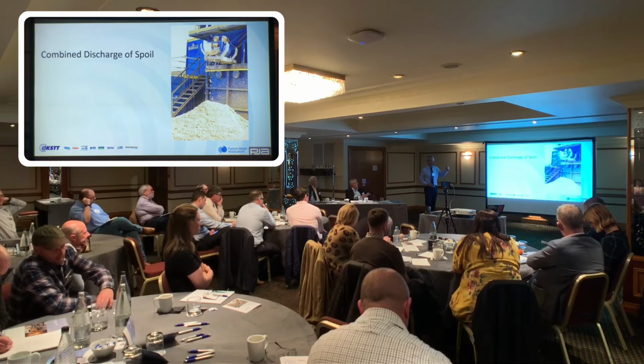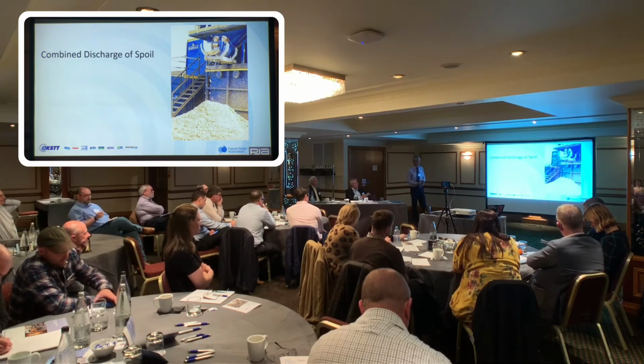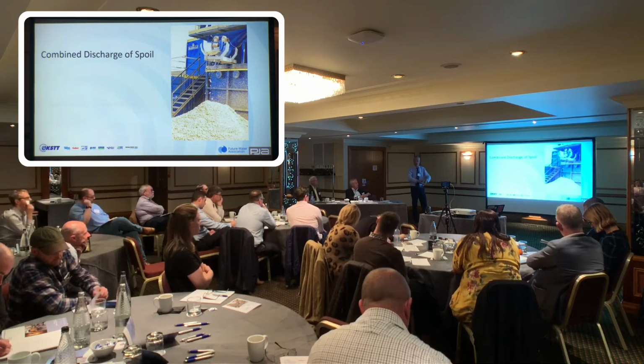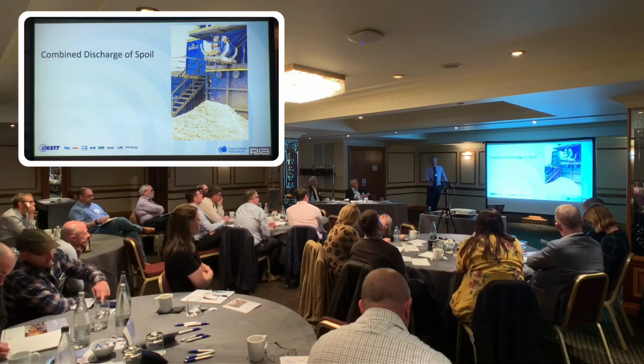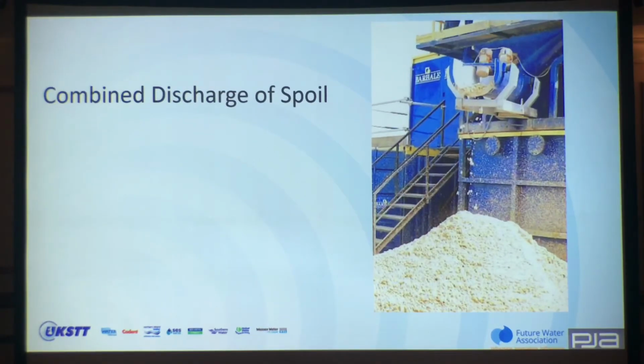And then after all of these processes, the spoil is recombined. So what you don't really want is all the gravel in one, unless you want to reuse it, of course. But for disposal, you would put the gravel with the clay, with the silt, such that you get a homogeneous material that's much easier to dispose of off-site. It's often got very high water content, which could mean you need to leave it to stand for a while before you can dispose of it. It's quite difficult to handle.